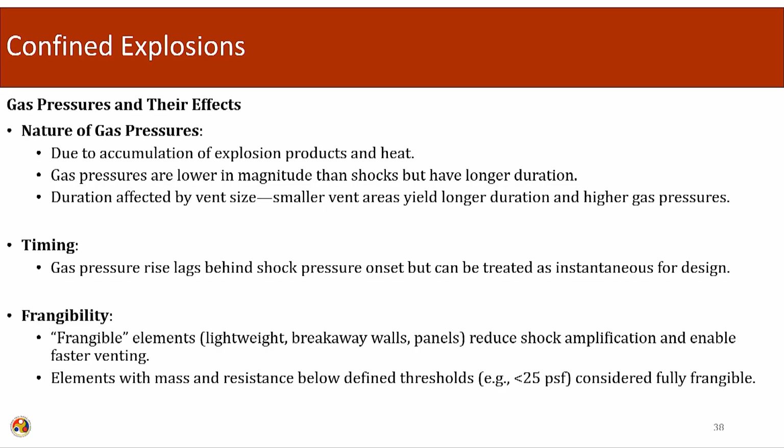So the effect of the gas pressures, what is the nature of the gas pressure? Due to the accumulation of the explosions, there is an excessive amount of heat produced. So the gas pressures normally are lower in magnitude than shock loads, but they have a longer duration. The shock load will dissipate faster, but it will have high magnitude. Gas pressure will have lower magnitude, but will take longer to dissipate. And the effect of the gas pressure is affected by the vent size.